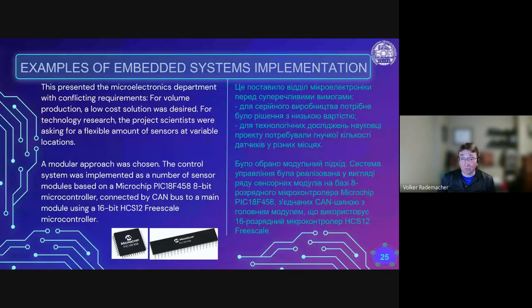It is a multi-master bus, so you don't have to worry about implementations of master-slave firmware. Most RS-485 firmware implementations are master-slave buses. There's a main module, and this main module has to organize requesting and picking up the data. That is an additional step to create a protocol for, whereas the CAN bus is by itself a multi-master bus that has its own bus arbitration and is deterministic, which makes it great for cars.